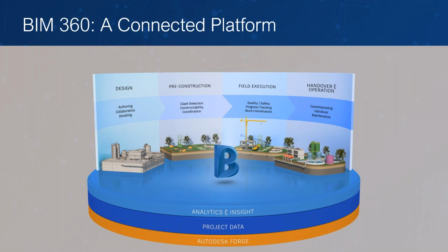So in case you're using a server based system, where you've got your local server on which you're aggregating your plant information and your Revit information, you need not worry about that space, because we're all working from home currently. We could take the benefit of BIM 360 Design in that case, and the information resides on the cloud. You've got facilities in Plant 3D to integrate with BIM 360 Design. And as I'm moving ahead with my presentation, I'll talk about how it could be integrated better.